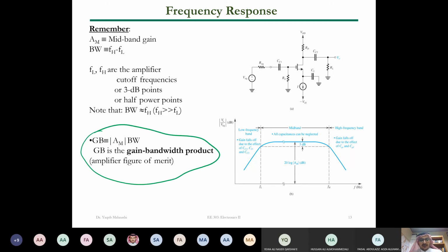This is what we call the gain bandwidth product. Okay, we have the midband gain, which is AM. As we agreed, guys, the AM is what we need, and the AM is where we need the amplifier to operate. Okay, the ALF and AHF are beyond the operation of the amplifier. This is just for you to know the attenuation at this point, for example, at this point here or this point there. But we are not operating our amplifier at these points. Okay?